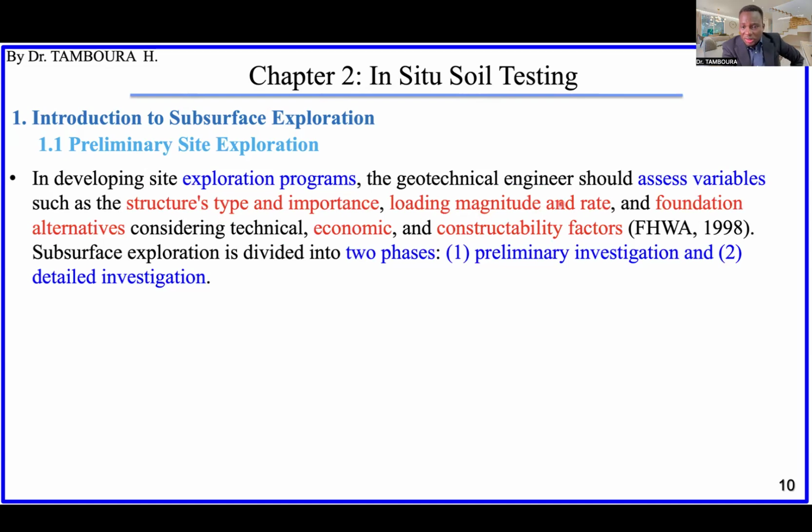The loading magnitude and rate, because if you know the type of structure, maybe you can judge the magnitude of the load that will be coming on your foundation. The loading rate may depend on the construction speed and everything. And the foundation alternative, considering technical, economic, and constructability factors.